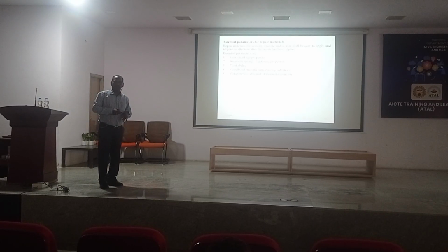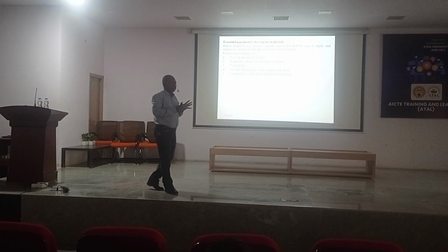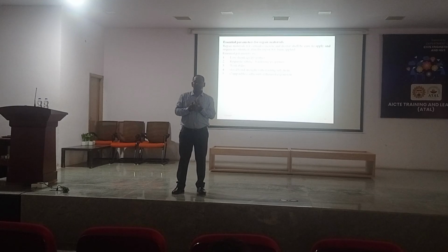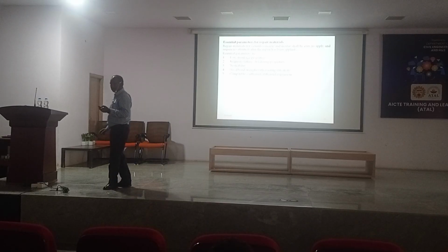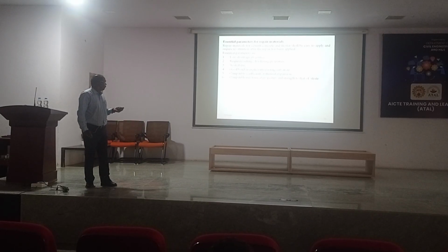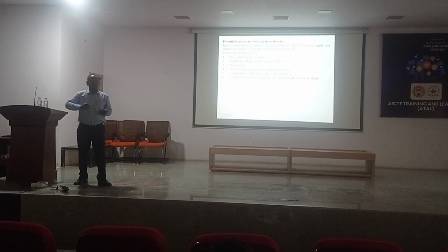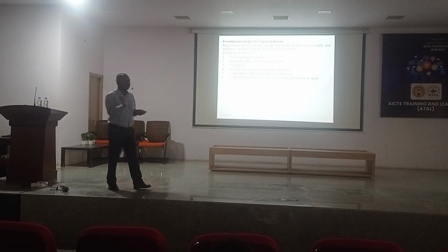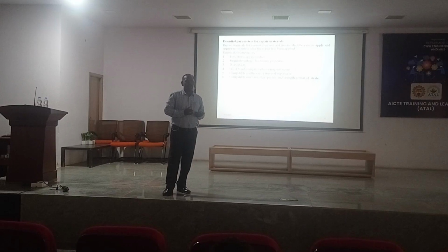Compatible coefficient of thermal expansion is sometimes very, very important, because you can select the repair material in such a way that the two materials have the same coefficient of thermal expansion. You cannot take materials with different coefficients of thermal expansion. Okay. Next one is mechanical properties and strength in the top strata. For example, if the old concrete is M30 grade and you add 50 megapascal concrete, it will not match, and you can get cracks again.